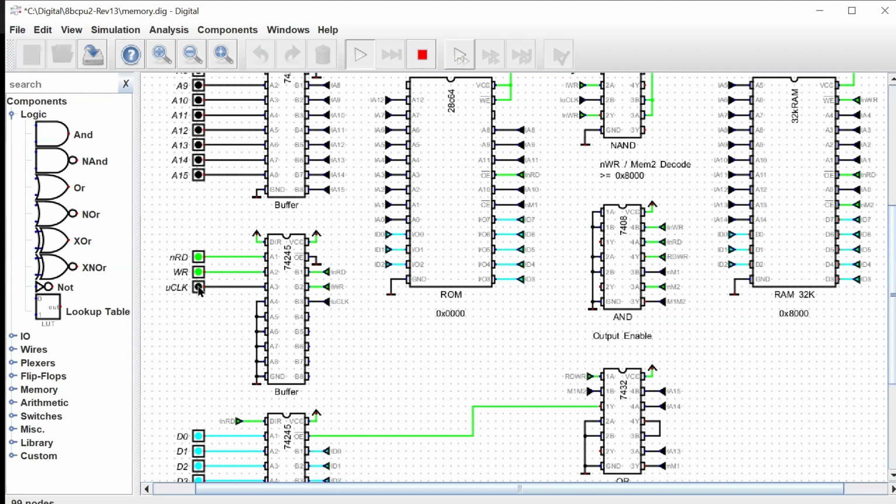And that's the issue right there. So right now, the data bus signal is high, which means it's not enabled, and the signals are disabled. And as soon as we do the U clock, now the data bus is active, but at the very same instant, we're trying to clock in what's on the data bus into our RAM. And that's the issue. That's a race condition. Those things are both happening at exactly the same time. And the output from our data bus driver chip might not be stabilized yet before it's being clocked into the RAM chip. And that's a race condition, and that's the problem.